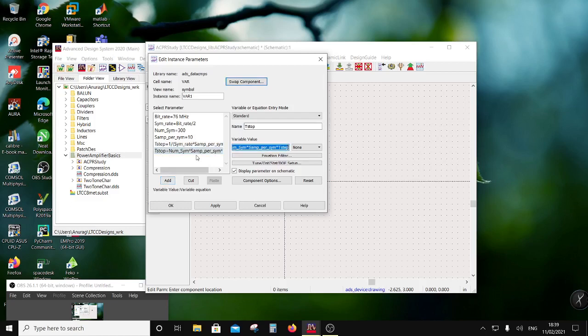Add stop time. And then you know that we are going to use some kind of a DSP filter. And a DSP filter is nothing but z minus 1, basically a delay by a sample, right? So basically a filter has a certain length of number of symbols or samples, and you specify the filter length as that. So this is going to be some form of a FIR filter, right?